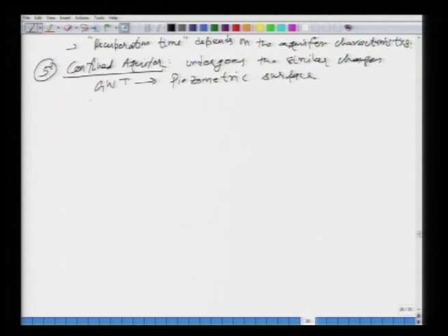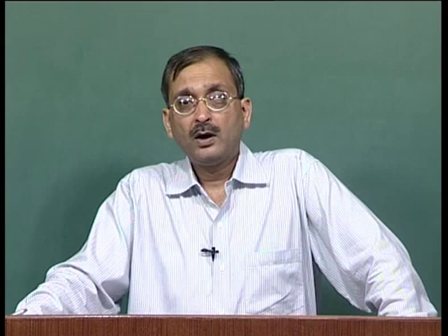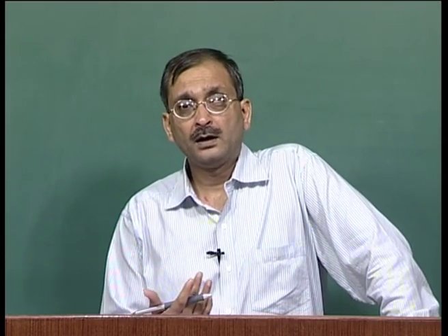The last note is about the recovery. In a confined aquifer it is very rapid, very quick, as compared to the unconfined aquifer. And why is that? Well, it is because the flow is taking place in a confined aquifer due to the pressure differences. So, this is about the process of pumping in well hydraulics.